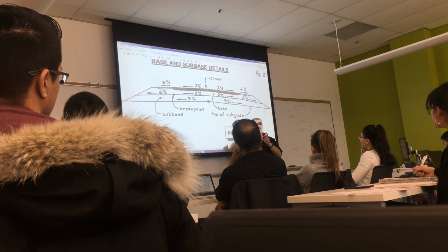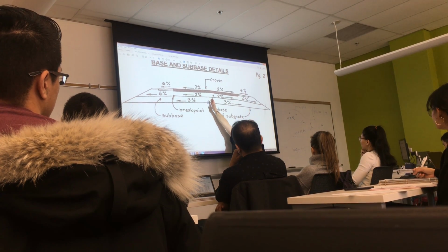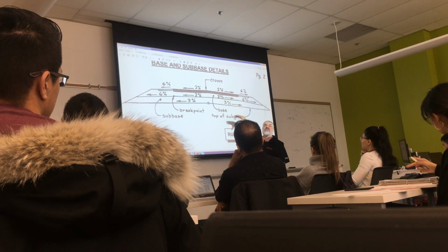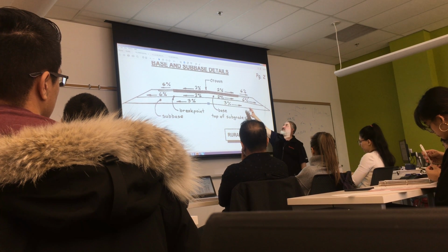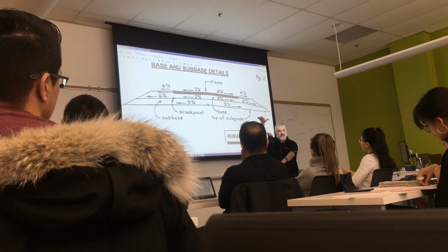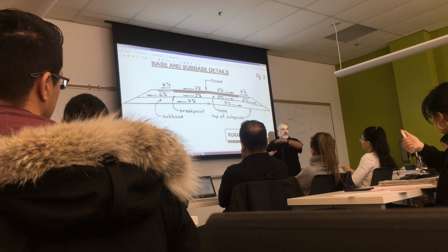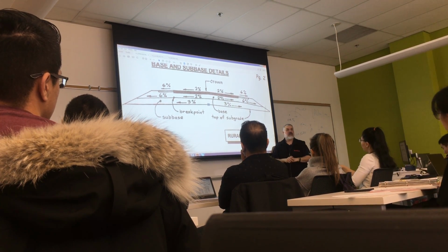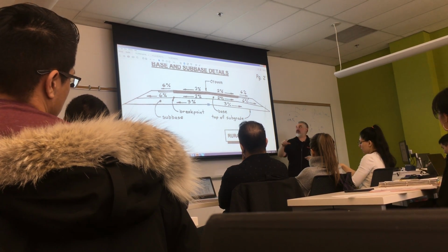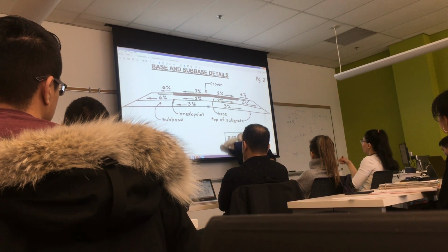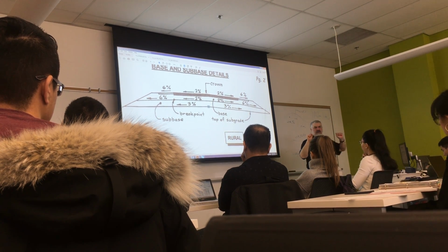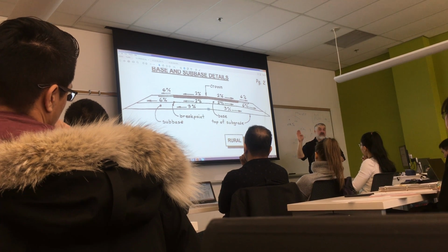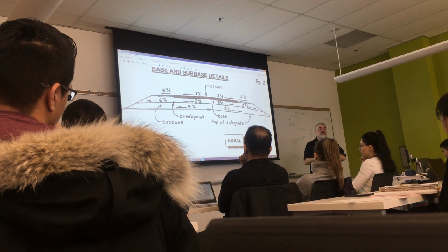So when you get a pavement design, those depths apply right in the middle. As you move away from center, depending on the crossfall of the different layers, you may have thicker materials. Okay? So this layer is typically always thicker because of this kind of divergence of two slopes, right? 2% on top, 3 on the bottom. As you move away from center, it gets thicker, and that's understood. So the thickness, when it comes to the design, applies right at the center. After that, it gets fatter, right? Thicker. Everybody cool with that? Right? So when I establish my depth of pavement layers, it happens at the center. And then beyond that, then these slopes take over.